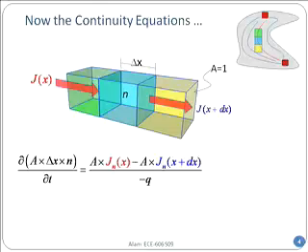Okay, so this is almost done. If I didn't have any other process, in fact, this would be the equation that tells me how many electrons are coming in and out. Now remember, these J sub n are the fluxes that are coming from the contact, right? These are drift and diffusion current. But of course, there is another current that we can also think of: if you shine light, that's a third contact from which electrons and holes can come, right? So in that case, assume that the top yellow arrow pointing downward is as if light is shining on that sample. So electrons are not coming from the contact, but coming from outside.